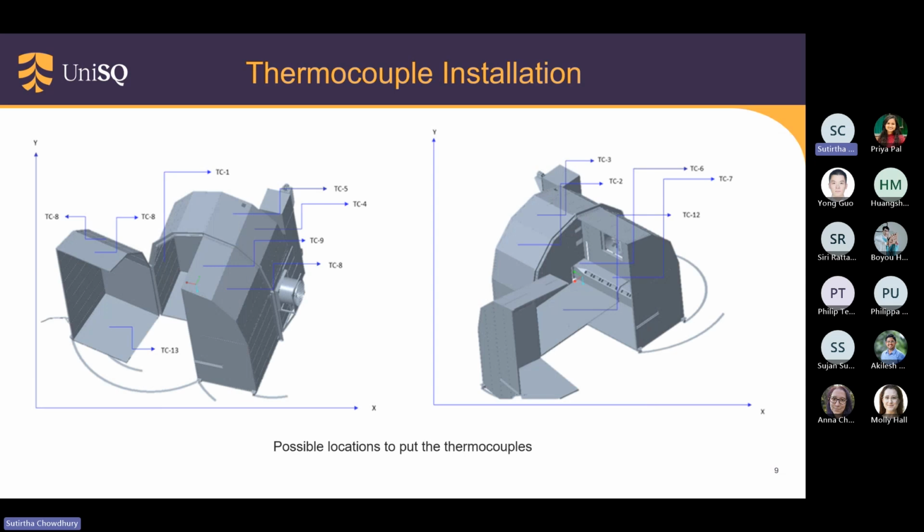we have already planned to put some K-type thermocouples inside the ovens to take the real-time temperature log readings. Here you can see the full graphical designs of the ovens. Here they have outlets in the back walls. They have a 6 meter long duct where they have 9 outlets. They have a recirculation fan, and I want you all to focus on the chimney because we are going to discuss the chimney size, the duct outlet numbers, and the back walls.